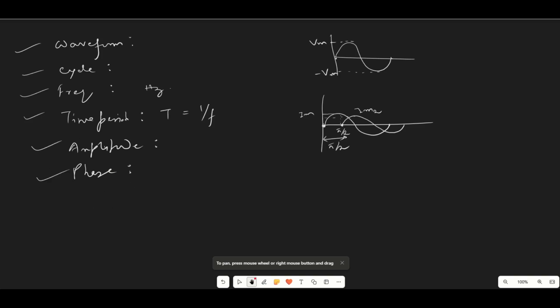Right. So now the next thing is root mean square. You have definitely heard of this term RMS, which represents root mean square. So what is the root mean square? Root mean square is the effective value of an alternating current, and it is defined as the value of DC current or direct current which will do the same amount of work in the same time, or would produce the same heating effect as when the alternating current is applied for the same time.